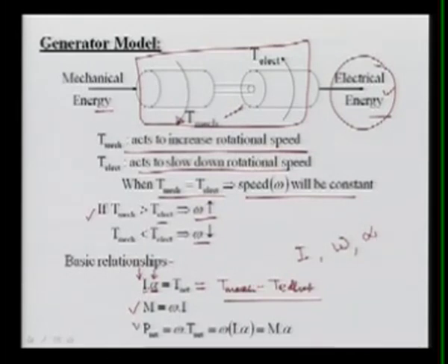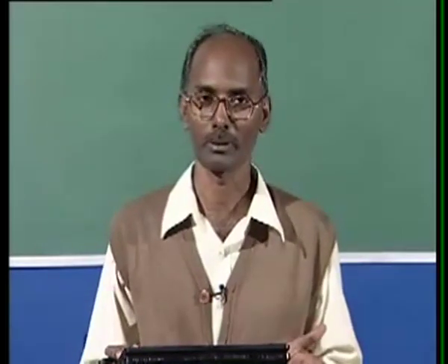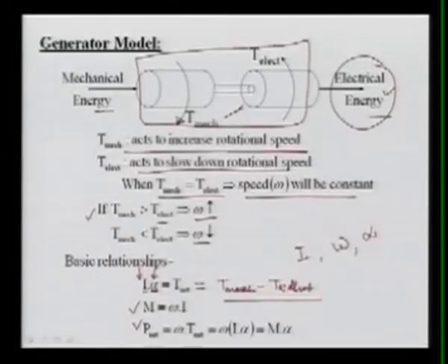Now this P net, as you know, this torque, if it is multiplied by speed, then it will give the power. So the torque and the power relationship is with this expression. Now if we put the T net value from this first equation here, and use this omega into I relation, we can derive M into angular acceleration, that is alpha, will be nothing but your P net.